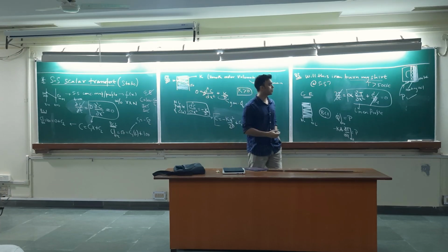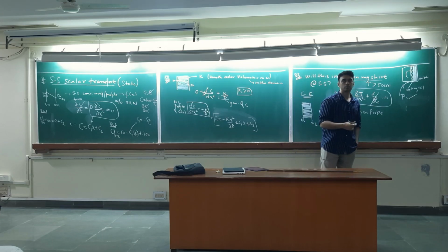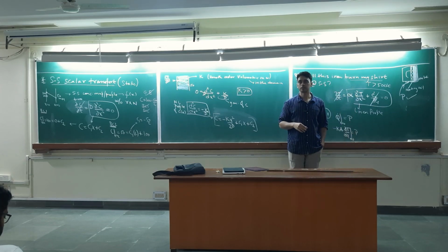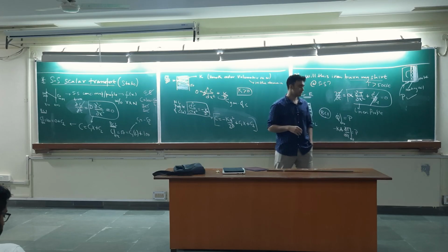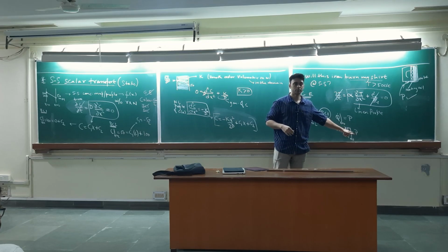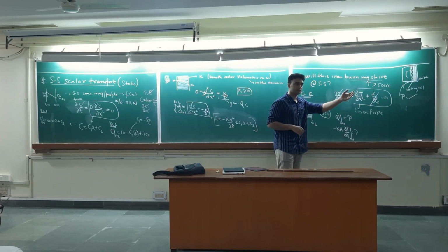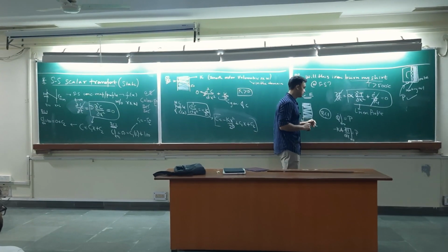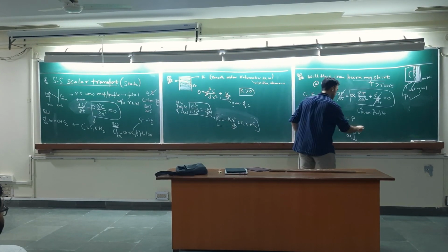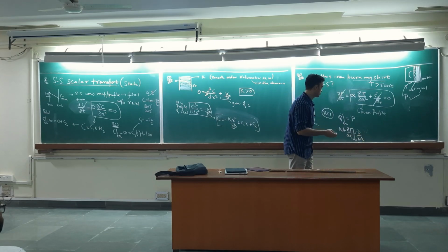If I had changed the problem to not this iron but some sort of a coolant which absorbs heat at a typical rate, then what would change here? Sign would change, right? The flow of heat would be in the opposite direction. So here it's positive, meaning it's towards the x. You have to keep that in mind. Okay, so we can convert this and write: dT by dx is equal to minus P by k A_c, with A_c for cross section.